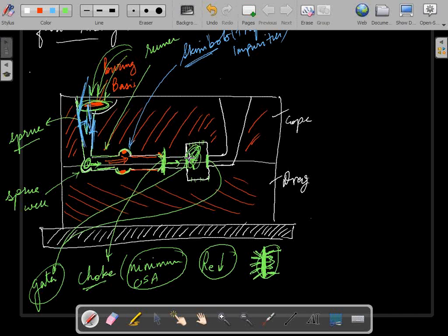After filling the mold cavity, molten metal then goes in this direction and comes up through this. Now this part is called your riser. Riser has many functions. I told you when liquid metal solidifies, it shrinks. When it shrinks, it decreases in volume.